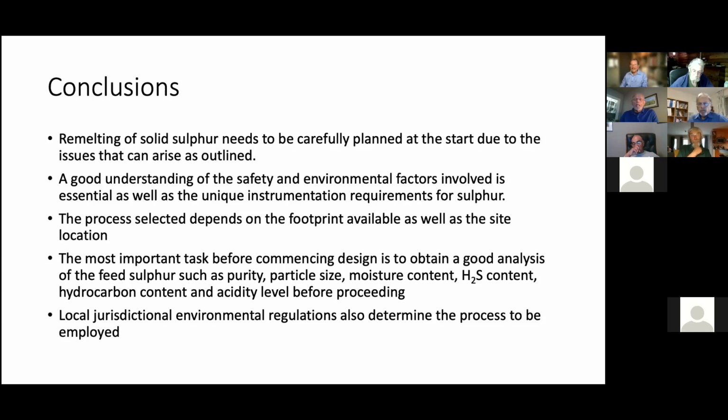So that's when we changed. We put in a grizzly. We put in a hopper with a 4-inch grizzly, so these guys couldn't dump large particles. They would backblade it into very sized particles, and we conveyed it very slowly and put a roof on, and vented the exhaust. That worked very well. We melted the block down to the base pad, and at the base pad, you're allowed to leave a meter or so of the sulfur on there.